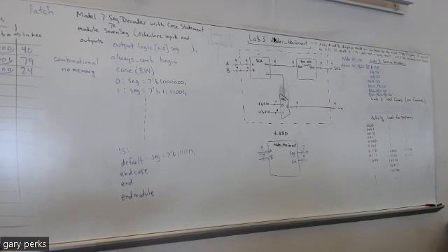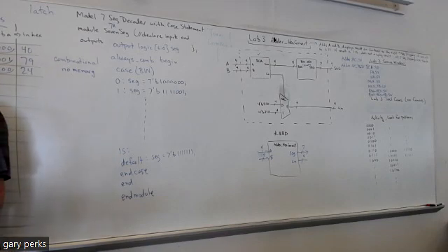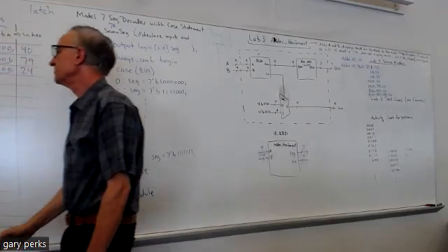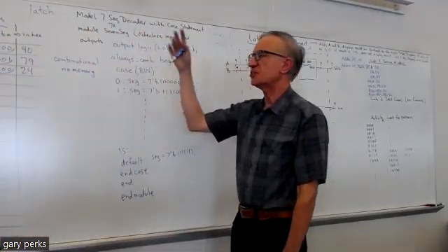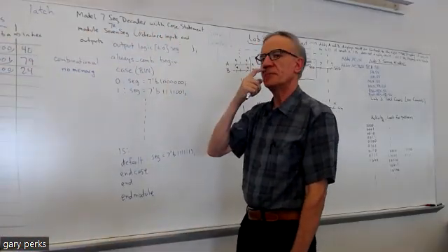So you'd have AN0, that would be the bit for that display. Then you'd have AN1 for the 7-segment display just to the left of the one furthest right. Then you have AN2, AN3. Likewise, you have seg0, seg1, seg2, and all that. Yeah, I'll show you in the constraints when we get to that part.